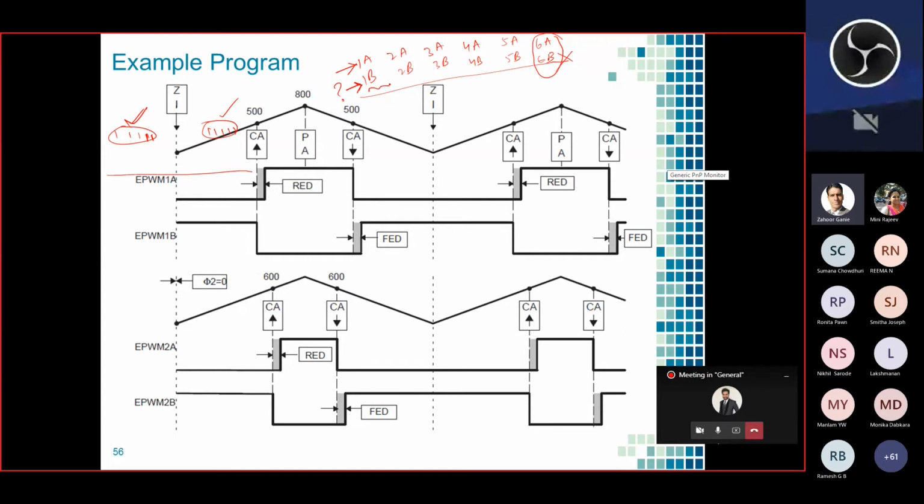But if I can generate 1A to 5A for the second inverter's top switches, till now we have seen that this is for the top switch, this is for the bottom switch. But if I could generate, by using this, 1B to 5B for the top switches, is it possible in the processor? So this is what we have planned to do, and successfully we have implemented that.